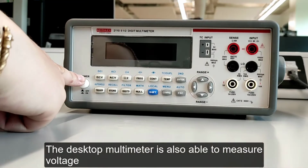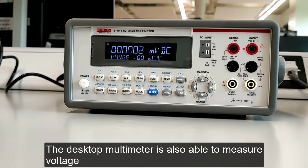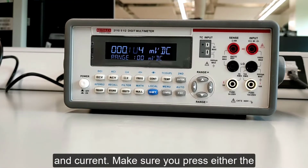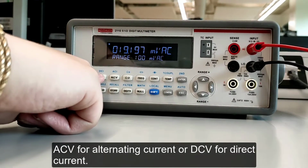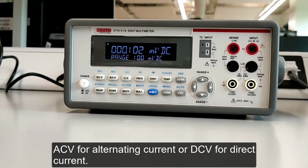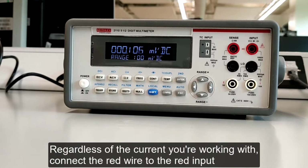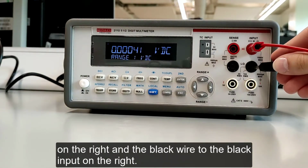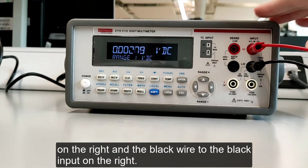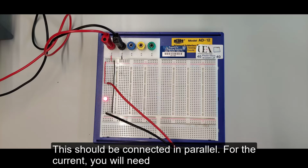The desktop multimeter is also able to measure voltage and current. Make sure you press either the ACV for alternating current or DCV for direct current. Regardless of the current you're working with, connect the red wire to the red input on the right and the black wire to the black input on the right. This should be connected in parallel.